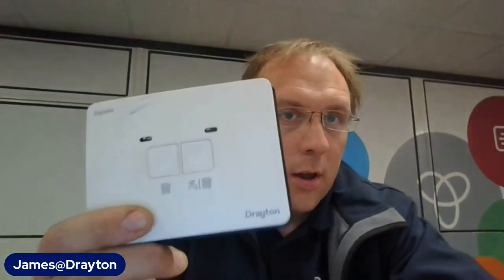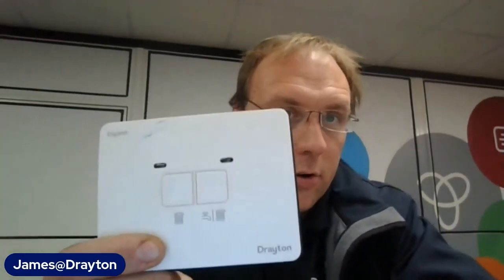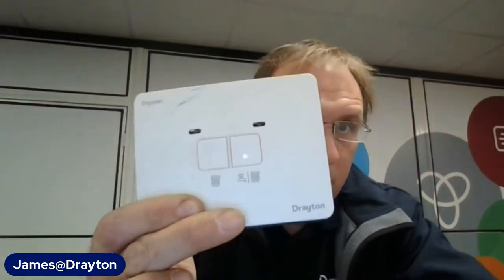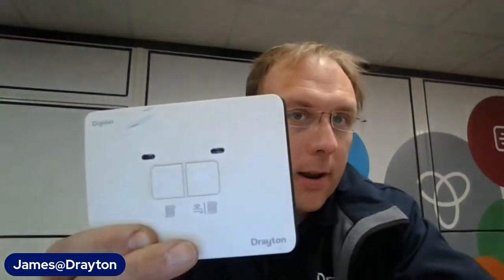It comes with the RF90T, which is the room stat, and you can use this to zone either a combi boiler, so you can assign 2 separate receivers to it, or you can have it whereby you control heating and hot water all off of the room stat. But the important thing with this is it uses the same backplate as, say, an HE722 or a 241, or indeed any of the 2-channel range of our programmers.